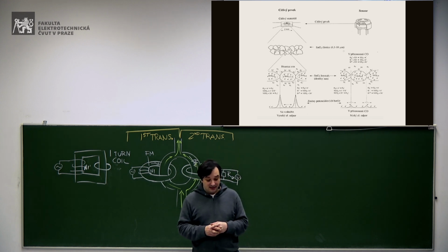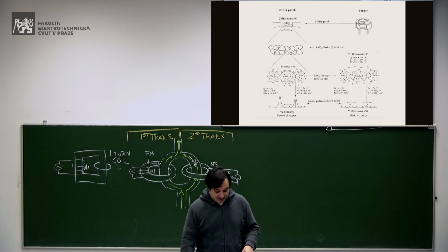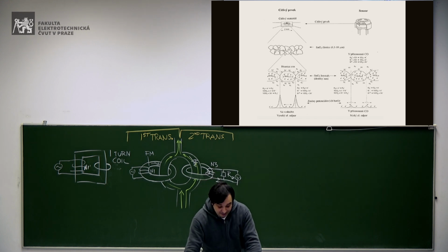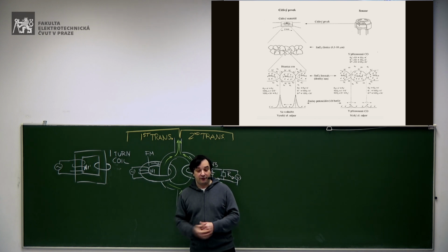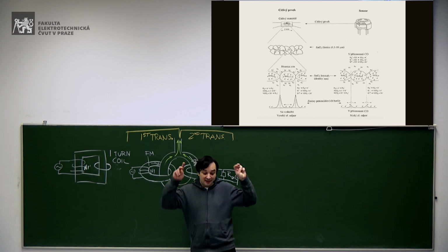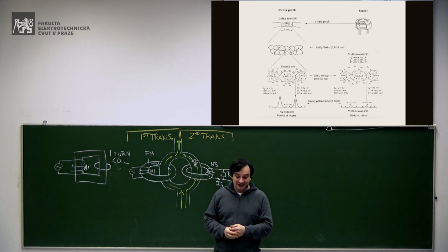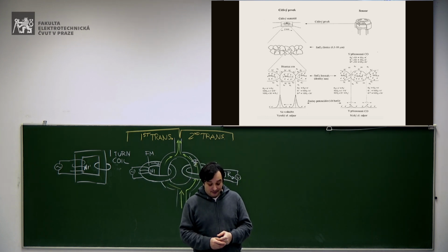Basically, if you have oxygen, this will create a depletion layer in the grains of the tin oxide. So the electrons move at the center of the grain, and you have some potential barriers for the current to go from one grain to the other, to jump from one grain to the other.